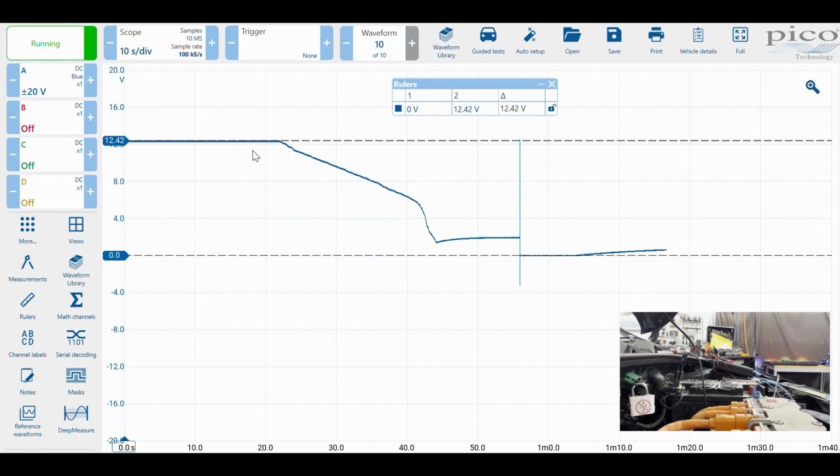So we found with electric vehicles that the jumper wire needs to be on for considerable time, just to ensure that that voltage does not creep back up again, and just repeat the test. So when you take the jumper lead off, it should remain at 0 volt.